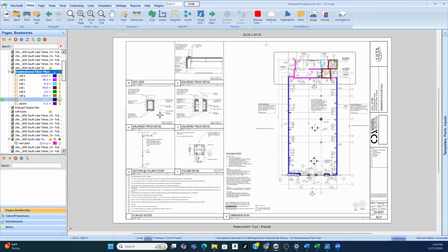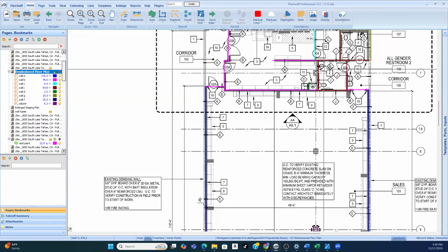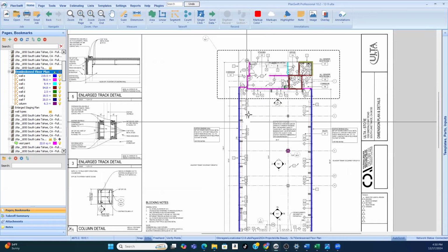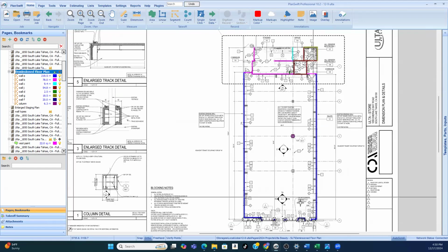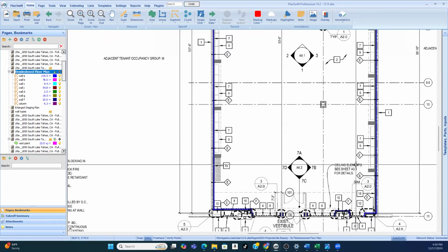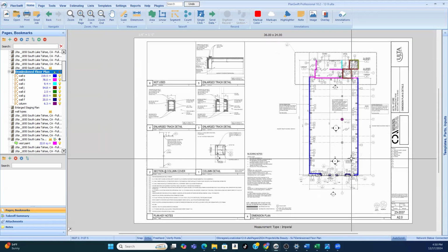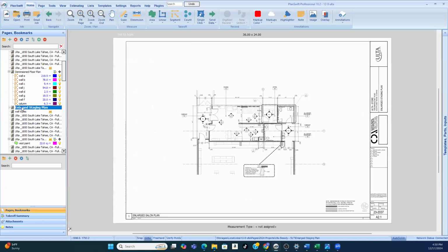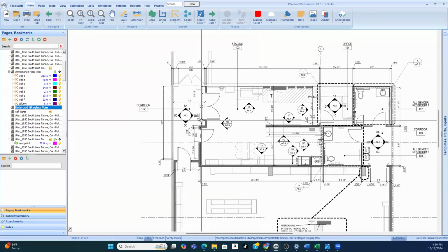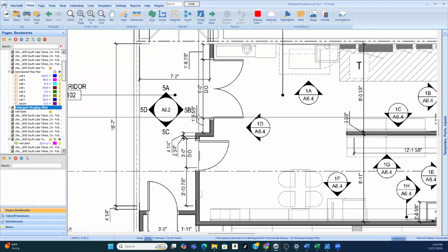So now we're back to we don't know the height of the wall for the framer, because we don't have good section views for this project. But other ones we will, and then it'll be easy to tell. That section view marker goes through the wall and it kind of gives us an idea of the height of that wall.